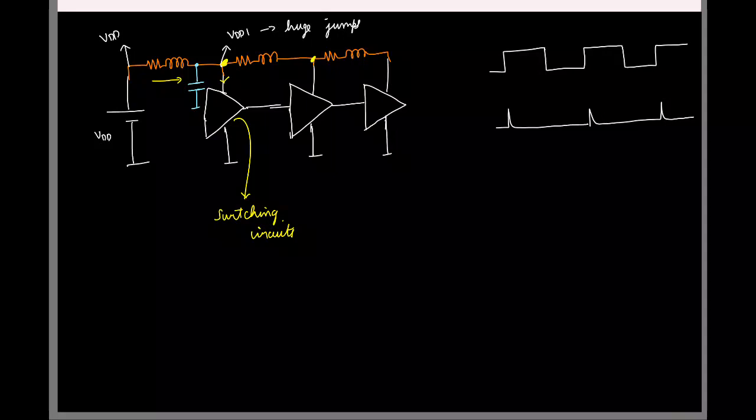And this is often called the supply bypass cap. This shouldn't be very surprising, because you know that if you have an infinitely large capacitor charged to some voltage, it behaves like a voltage source.